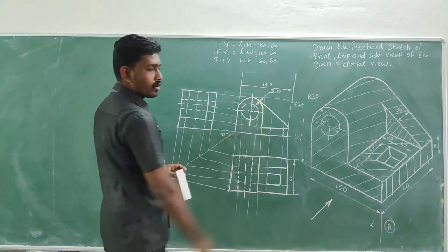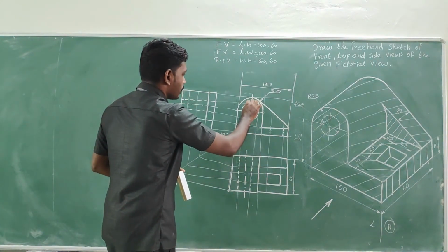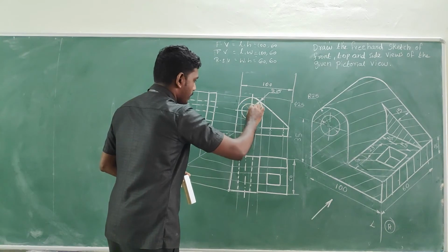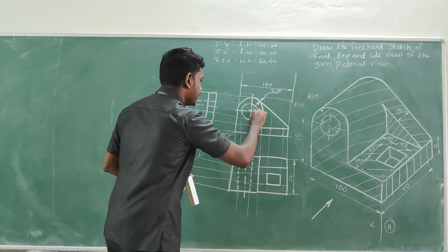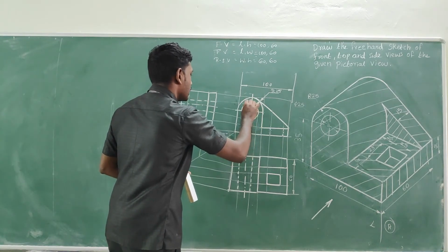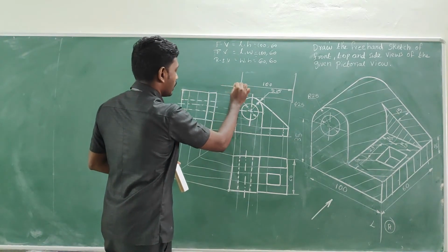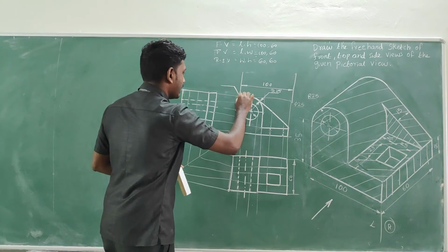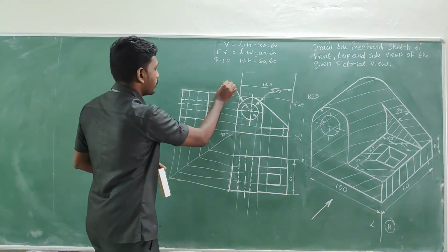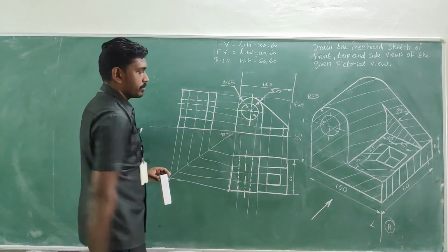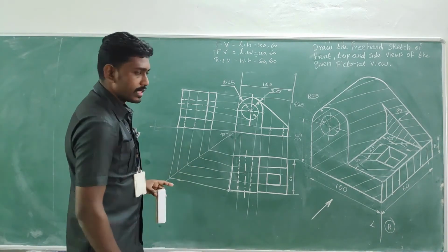Then there is a hole which is diameter 25. For which go for a diagonal line like this. So for diameter, capture both end arrows, and try to pass it through the diagonal of it. Okay, take a leader line like this through the diagonal and write above the leader line diameter 25. Okay, and then what all the things are there?